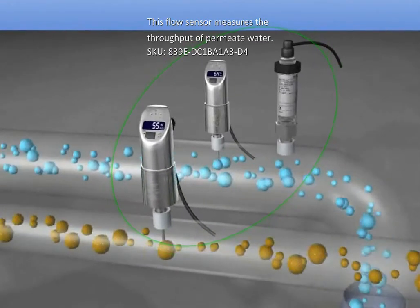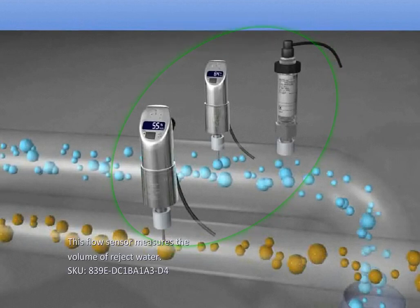On the output side of the filtration skid, we have 2 flow transmitters, one on the permeate water pipe and a second on the reject water pipe. Both the 839E flow sensors have been individually calibrated for high flow and low flow settings based on the diameter of their respective pipes. The flow sensors at the output end of the process are used to measure the total throughput of the filtration system in gallons of water. The flow sensors display 100% when there is maximum flow through the pipes. A lower percentage is used as an indication of decreased throughput at the output end of the system.